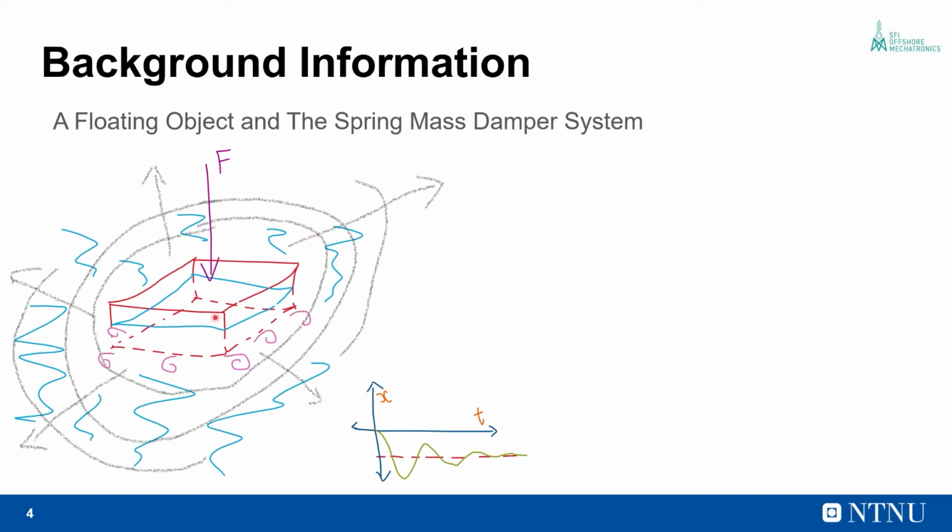We see that as the barge moves down, it pushes water away from beneath it, and as this flow leaves the surface, there is flow separation and eddies are formed, and this causes the energy to be dissipated in the form of heat to the surroundings. And these are the two phenomena by which energy is transported away from the system and the amplitude of this oscillation decreases.